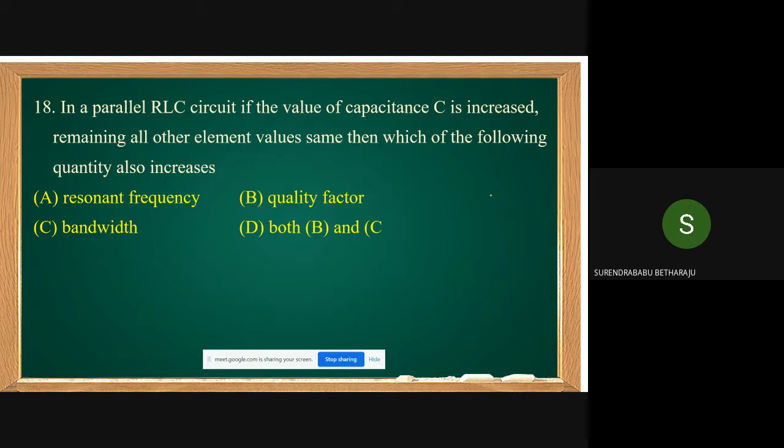First we will see. Omega naught equal to 1 by root LC. If the capacitance increases, the resonating frequency decreases. That means the resonating frequency does not increase. That's why option A is not the answer.